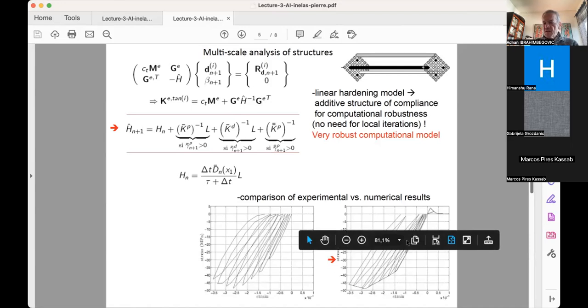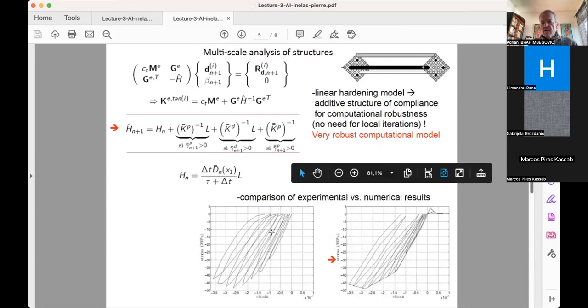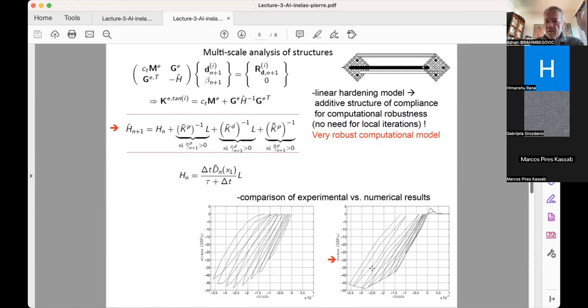And what we reproduced by using our model is this diagram over here. So you can see that these nice curvilinear hysteresis loops and these piecewise linear rhomboid types of structures are not the same in terms of shape, but at least we try to have the area on each and every one of these loops be as close as possible. And also to reproduce the salient features when damage kicks in and softening starts, and so on and so forth.